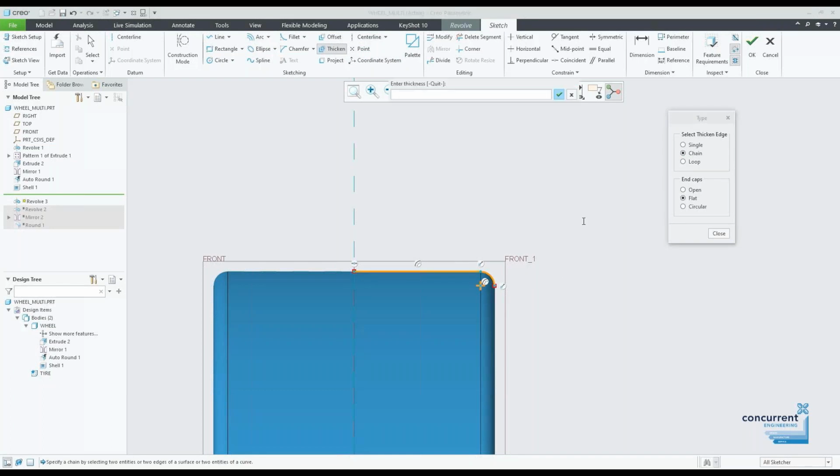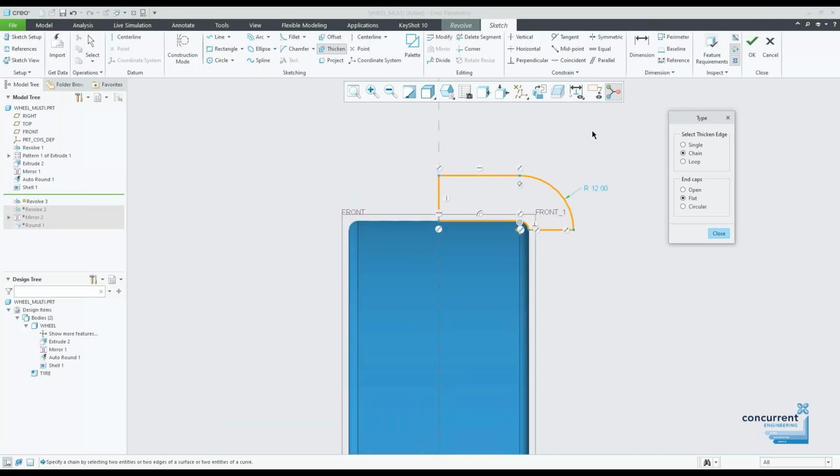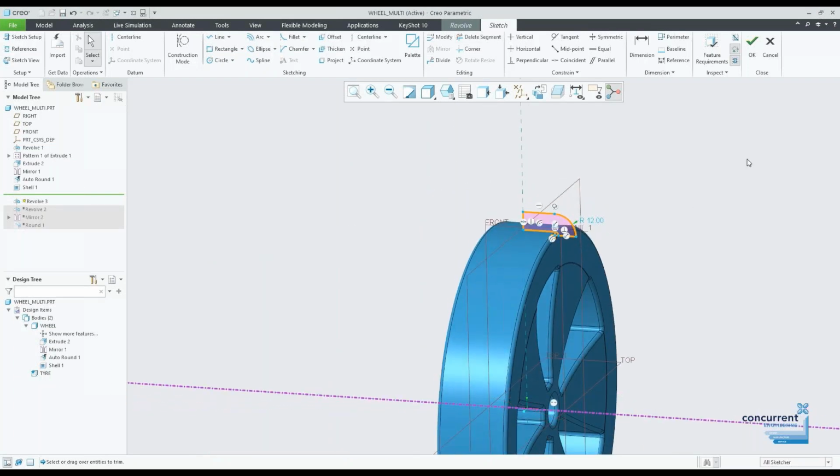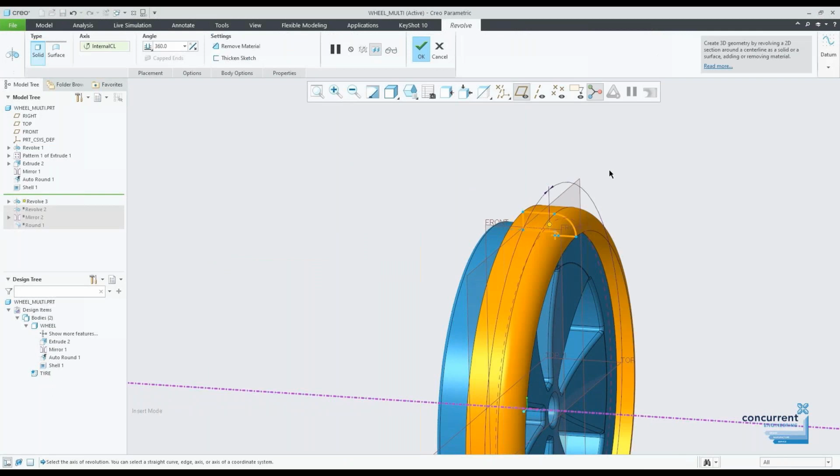That one. Hold down control, get the second, thickness of 10, and then it's pointing downwards, so I'm going to do -10 as the thickness of the tyre itself. So I'm happy enough with that. And you can see what's happening is we're getting the shape being filled out. Now what we need to do is make sure that these initial lines here are taken out. Okay, so we're just going to delete out that one, and you can see that we actually get the full there. All right. Now that, as we know, is fairly straightforward, but what the options we have here is this body.